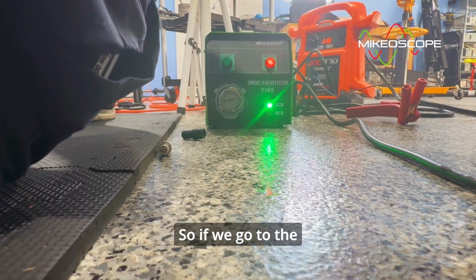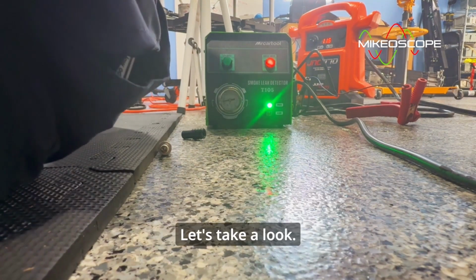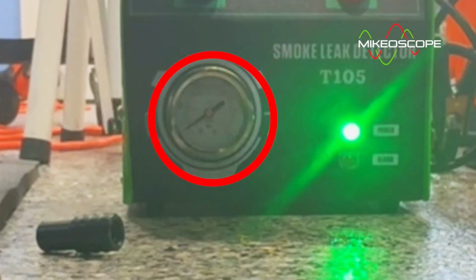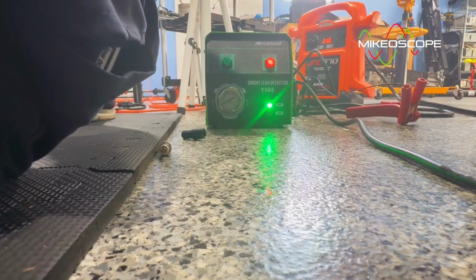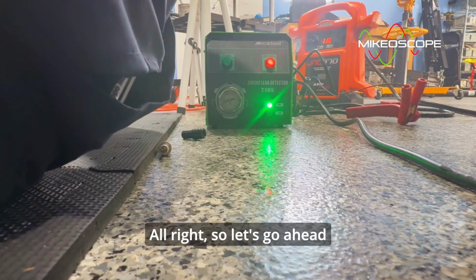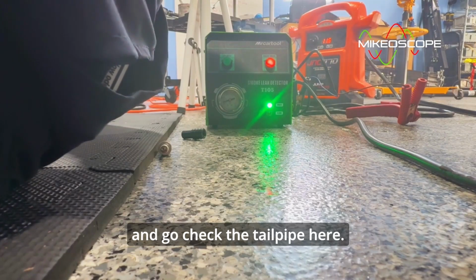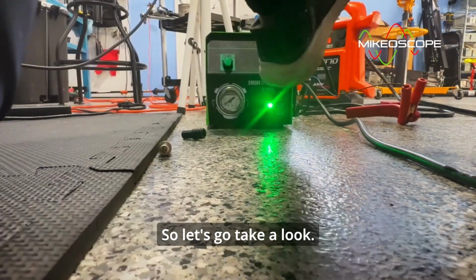So if we go to the tailpipe, we should see smoke. I'm gonna try to activate the valve again. Let's take a look. You see that? The pressure dropped. Okay, so turn it off. And the pressure should do it again. So this shows that the valves are working, okay? All right, so let's go ahead and go check the tailpipe here. Okay, this time I expect to see smoke at the tailpipe, so let's go take a look.